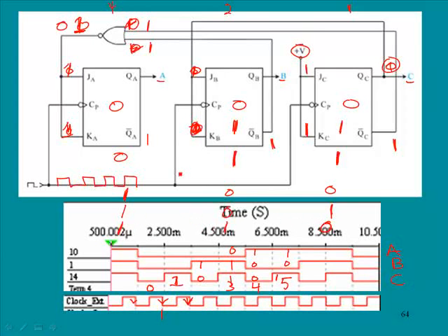And again, okay, we're at 1. Now we're at, let's see, I had to find a place to write these. I guess we'll just write them down here. We were at 1, 1, 0. That gives us our count of 6. And since we're at 0 here, on the next count, this will not toggle because there's zeros on the B. C will always toggle, so then we'll have 1, 1, 1.